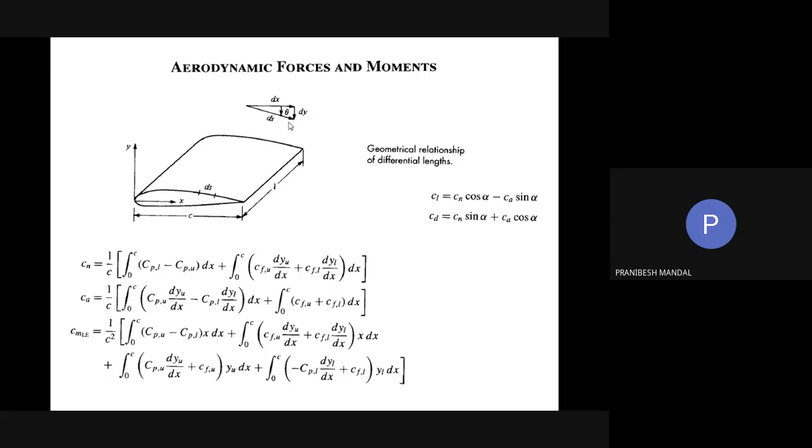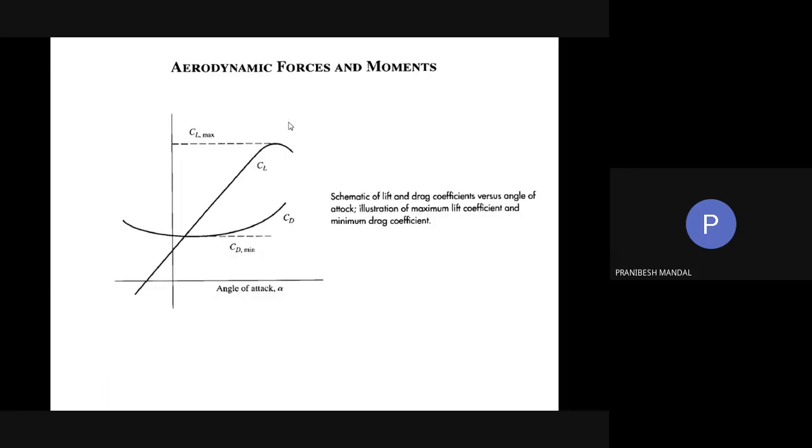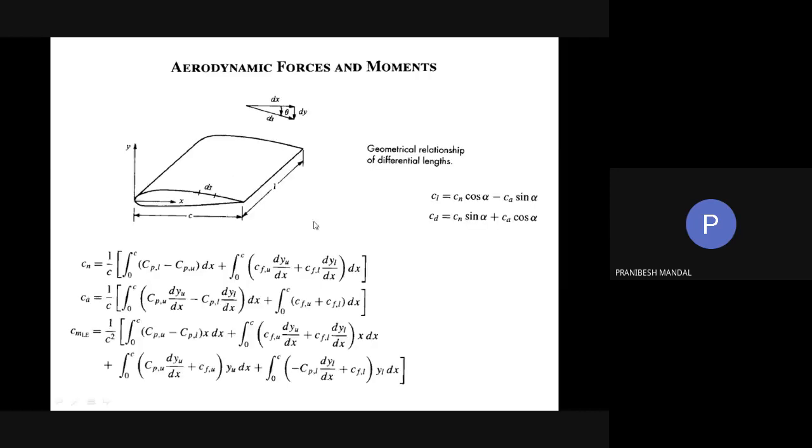So as I mentioned, we can use these particular things if other conditions are prevailing. Obviously, the other conditions must come in the picture. Before that, this is the general characteristics of drag and lift coefficients. Drag and lift coefficient can be very easily found if we find the normal and axial force coefficients using these two equations. The relationship between lift and drag, and the relationship between the coefficients, are obviously the same. So if we find Cn and Ca, we can obviously find Cl and Cd.